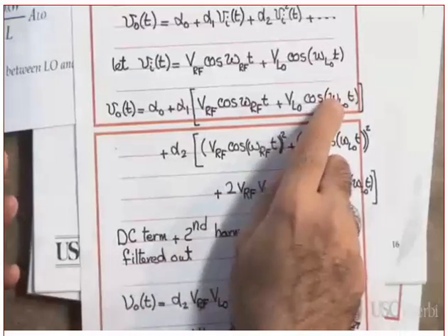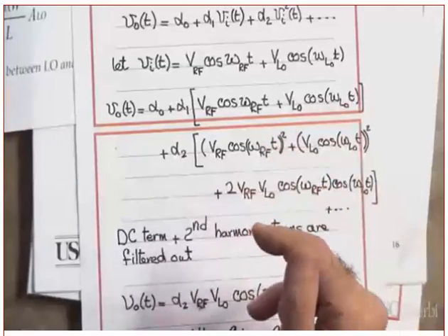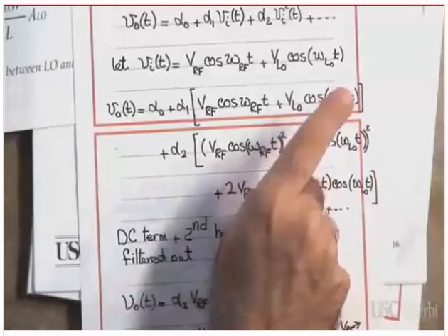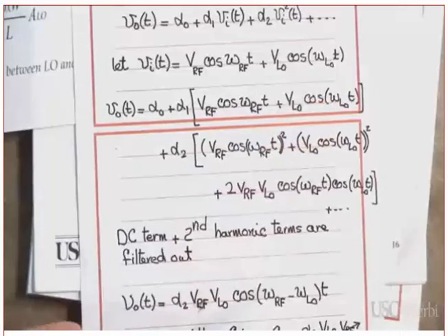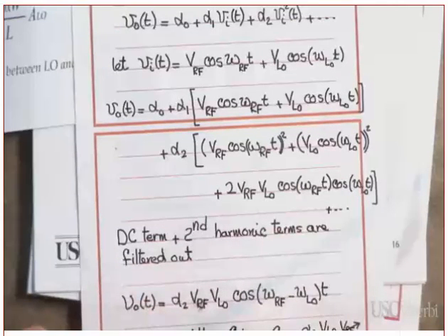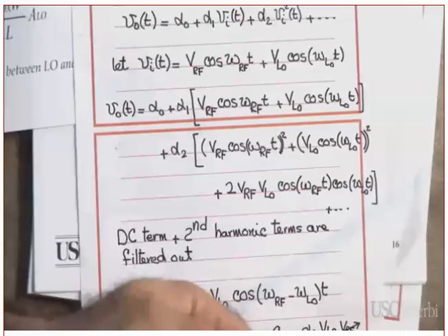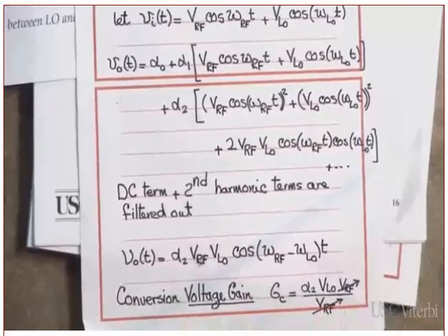So, as long as I use a periodic signal whose period is the same as the sinusoid, then I'm okay. Did you get my point or not? Now you might say, but Professor, why are you using a periodic signal rather than a sinusoid? We already have an advantage of using a square wave, plus or minus polarity, in that the fundamental is a little bit higher than the sinusoid for the same peak to peak. Did you lose me?